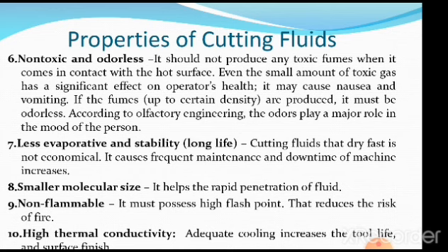Less evaporative and stability means long life. It should be less evaporative. That means it should not evaporate very fast. In other words, it should not have a very low boiling point. It should have a high boiling point. Cutting fluids that dry very fast are not economical. It causes frequent maintenance and downtime of the machine increases.